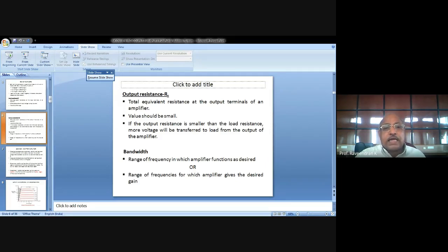So to make the transistor work as a common emitter amplifier, it is to be operated in the active range. That is, base emitter junction forward biased and collector base junction reverse biased. That is the DC condition to be maintained in the transistor circuit. This biasing is done with the help of a voltage divider biasing network R1 and R2 as shown in the figure. In the absence of the signal, only DC voltages are present in the circuit. The DC collector emitter voltage VCE, the DC collector current IC, and the DC base current IB are the quiescent point of the amplifier, that is, the Q point of the amplifier.